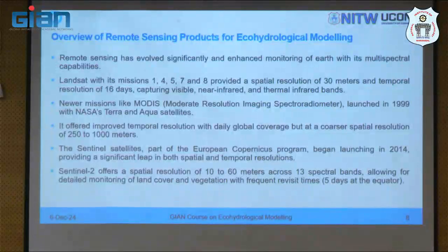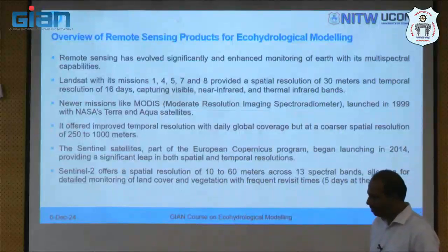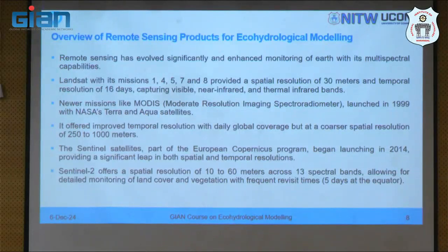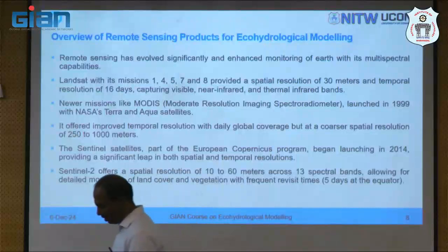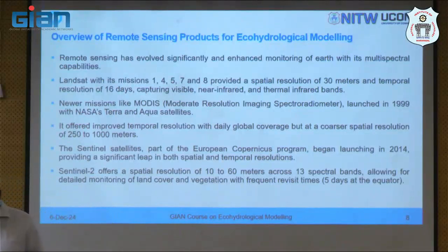It has both microwave remote sensing products as well as electromagnetic spectral bands, 13 spectral bands, right? For detailed monitoring of land cover, vegetation, frequent visits. It has a frequent revisit time of 5 days, but this data is available starting from 2015 to 2017 or so. 2015 is Sentinel-1, and then 2017 is when your Sentinel-2 and other images have come.